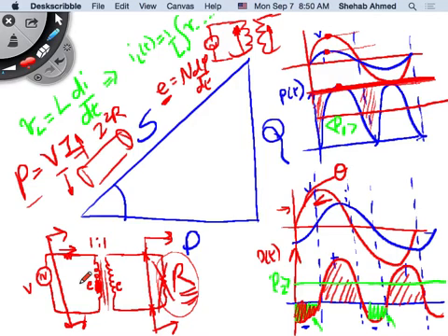This current is flowing through cables. Right? These cables have resistance or impedances. They will cause voltage drops, they will cause power loss, and they're not contributing to average power transfer. So typically, the more reactive power you have in a system, is it good or bad? If you have a lot of reactive power in a system, is it a good thing or a bad thing? We said it does not contribute to average power transfer, to motor torque on the shaft, to light production, or to anything we want. It's something that we have to live with.